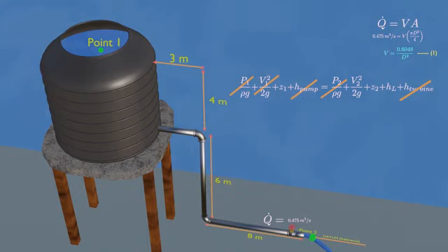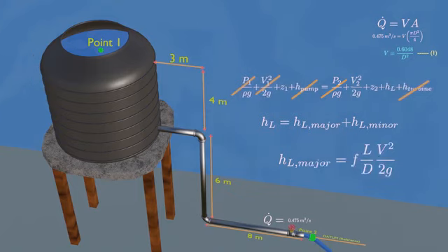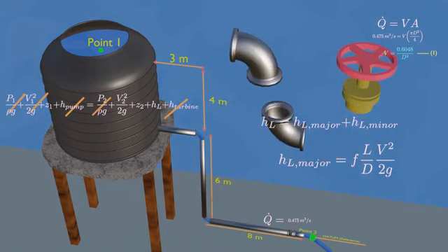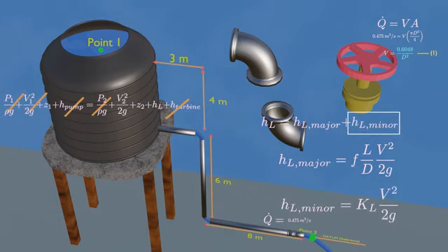When designing pipe, you must account for two types of losses. One is major head loss, and the other is minor loss. We can calculate major loss using this equation. In addition to this, head losses also occur at pipe connections, such as bends, fittings, entrances, and transitions. These are called minor losses. The formula for calculating minor head losses.